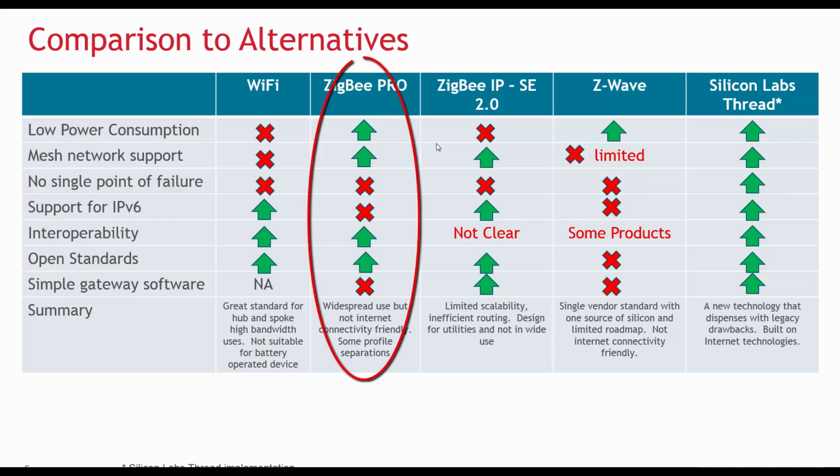Next we have ZigBee Pro, an 802.15.4 based mesh networking standard used in Silicon Labs' Ember ZNet stack offering, and one that has seen steady growth over the last decade. ZigBee Pro addresses the shortcomings of Wi-Fi and positions itself much better for a widespread network of interconnected, low-power devices that don't require nearly so much bandwidth, and that makes it similar to Thread, except that ZigBee stack layers aren't IP-based, nor is its application layer, although the ZigBee Alliance has announced plans to rectify that.